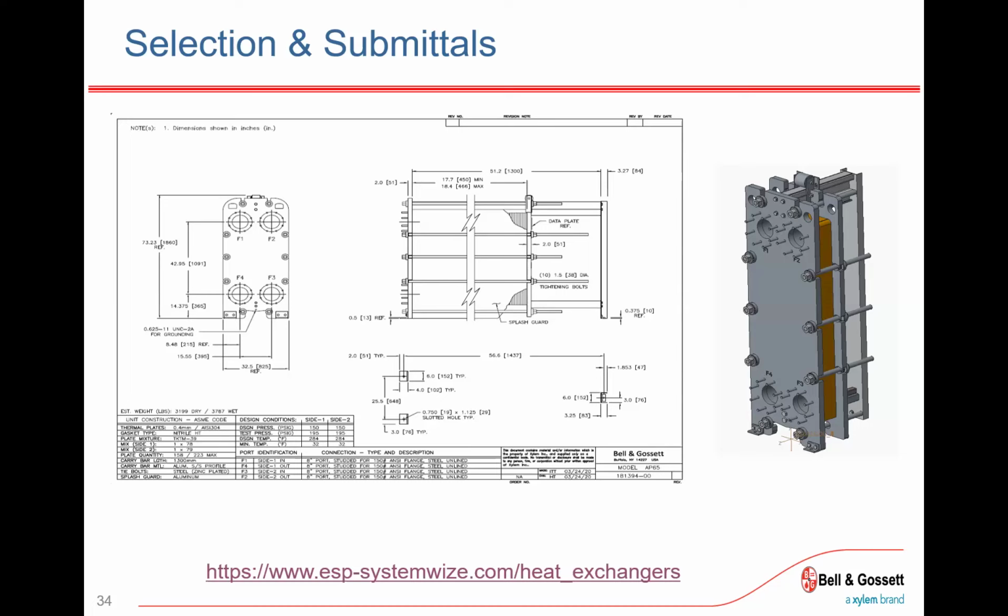So let's say if I were to look at this one, it provides your wire to water efficiency. The reason for that is because the motors aren't rated separately. They're just the whole package. So hydraulic efficiency and motor efficiency are all factored into that. Here's that RPM. We have our NPSHR, our horsepower, and our relative price. So what you can often do is say, okay, I want to sort by relative price. What are a couple of these where it's 74%? That looks pretty good too.